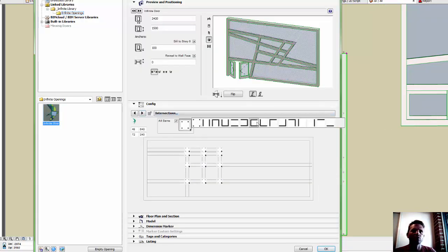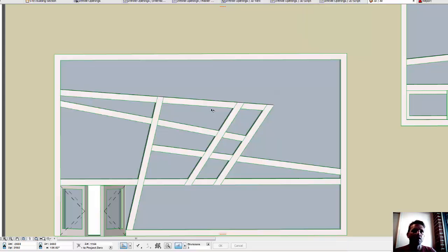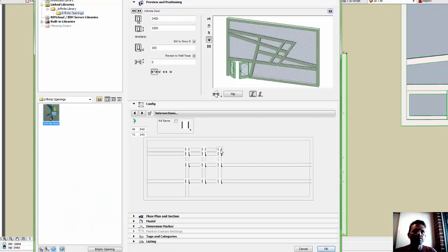I'm just going to set them all to mullion dominant. So that's how it would look if you did the whole thing mullion dominant. For these areas, we want to create nice corners. So let's go back in and do a bit more fine tuning. So if I turn that off, let's put a corner up here. Let's put a top edge on this one and on this one. Here we'll have it neutral, side edge on that, neutral again in this junction, bottom edge here, another bottom edge, neutral in this junction and neutral in these junctions in here.